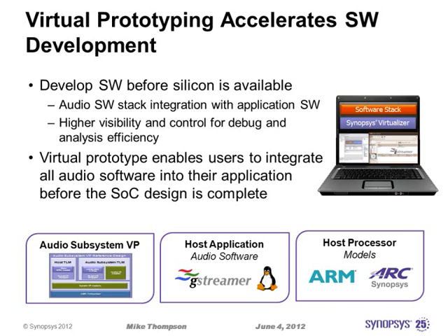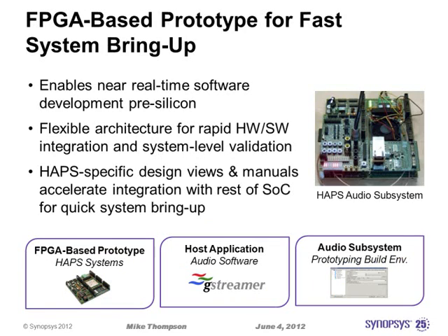So you could potentially implement your whole system in a virtual environment if you wanted: the host, the audio subsystem, and everything. You could split them, implementing the audio subsystem in FPGA and the host environment virtually. It's up to you. It's a very complete environment, which makes it very easy to develop the host application using the subsystem. As I mentioned, the demo itself is built up on a HAPS environment where we implement an ARC host environment supporting the audio subsystem. And I'll have that up here tomorrow.